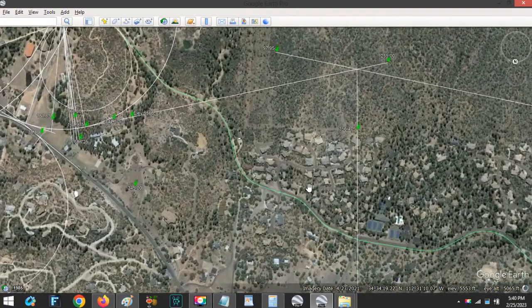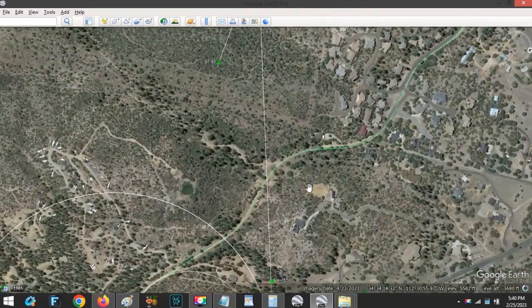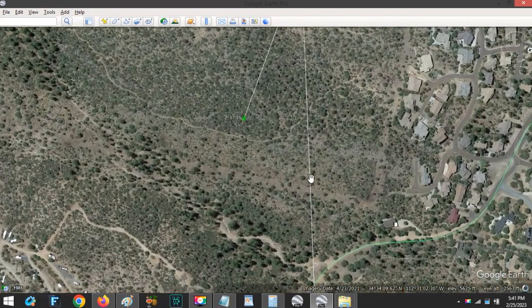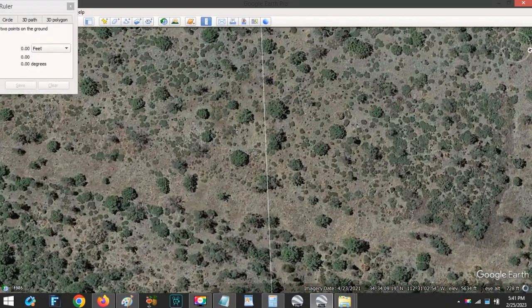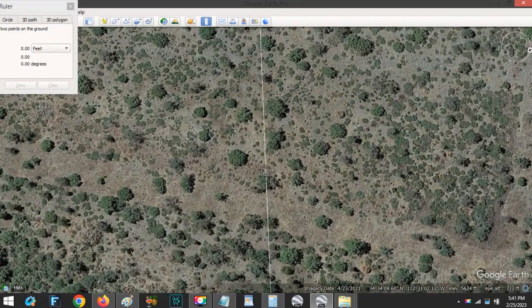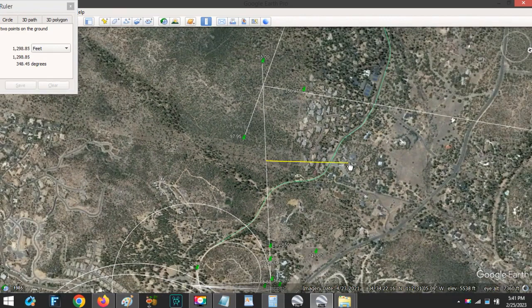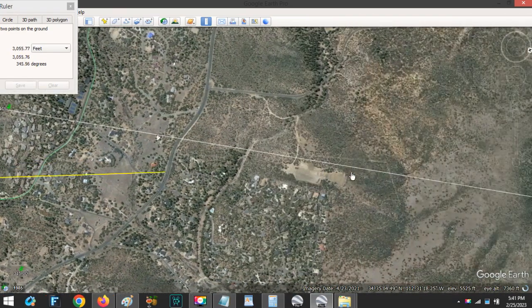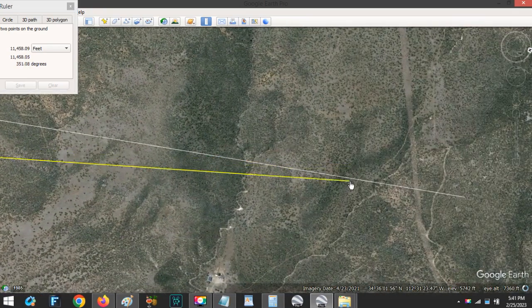So I guess now we'll draw the first radial line. I always draw them on the left. This curve is going to be 12,500 feet. So this is how you establish, once you've established the center line, this is how you establish the radius of the circle.